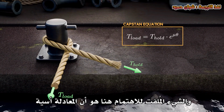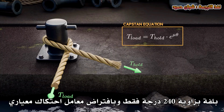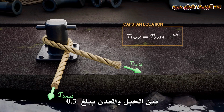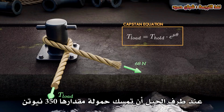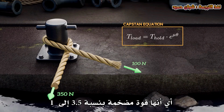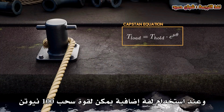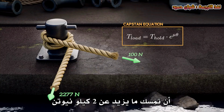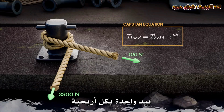The fascinating thing here is that the equation's exponential. With a turn of just 240 degrees, and assuming a typical rope-to-metal coefficient of friction of 0.3, the post allows a 100 Newton pull on one end of the rope to hold back a 350 Newton load. That's a 3.5 to 1 force amplification. Use an extra turn of the rope, and the 100 Newton pull can hold back over 2 kilonewtons, meaning you could hold up the weight of 3 friends with one hand pretty comfortably.